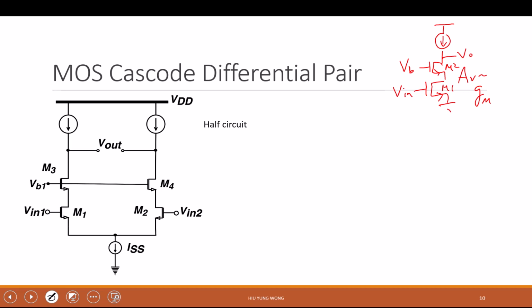What's the gain of common source? Yeah, negative. If I have ideal loading, it's just GM RO. Now Cascode, what is that? Why is it so great? Square. It becomes GM RO square. Or we can say that this is approximately equal to GM1 RO1 GM2 RO2, which is GM RO square, if they have the same order of magnitude.